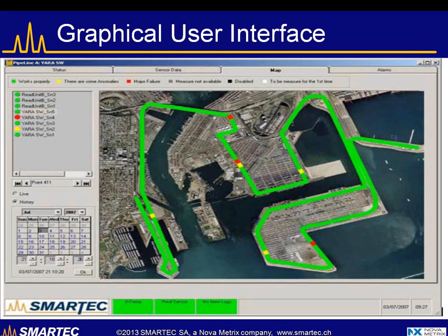For example, here you can see the red and the yellow dots locate the warning and pre-warning locations. It's also possible to segment the length of cable in sub areas, as you can see in the panel on the left, so that it's possible to immediately notice in which area of a plant or a dam the alert is being generated, and so different actions might result from alarms generated at different locations.